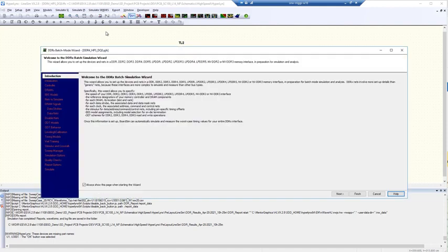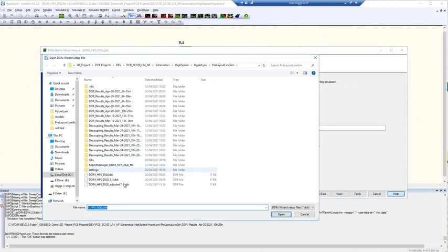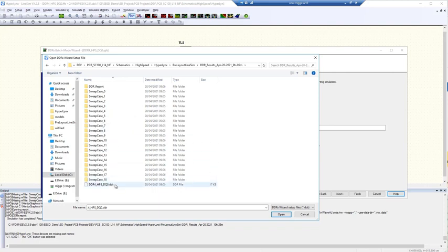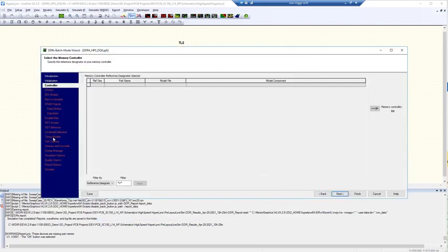The goal here is to find the tolerance between the DQ and the DQS nets, and then provide these constraints to my teammates. There's a lot of what-if analysis here, seeing what works and what doesn't work, trying out tolerances and ruling out others. This upfront simulation work that I'm doing will save my teammates a lot of effort down the road, knowing that the timing of the DDR signals are correct and the signal quality is sound.